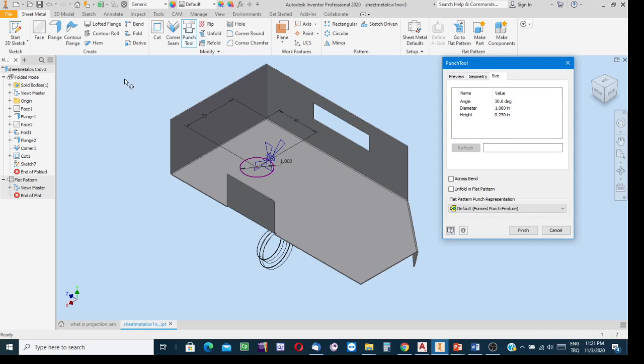Although at the beginning it is strange, but it is a fact. At the beginning we selected the metric unit system. For this facility, the size values you see are shown in this pane in the British unit system, inch. Diameter of the circular emboss is 1 inch. Height, meaning depth of the emboss, is 0.25 inches.